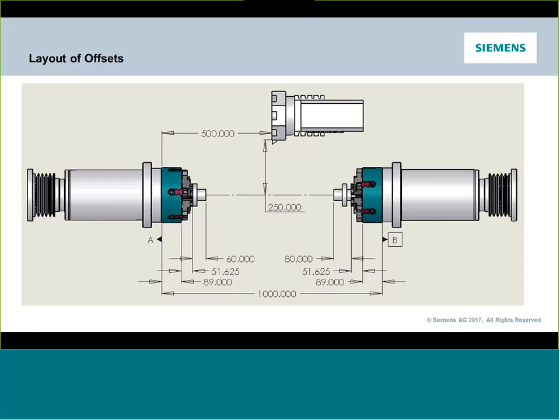Last thing we want to do certainly is be able to catch a tool while we're doing our transfer section. Now, the input is typically going to be set to diametric for X. So when we actually type in the value, you'll see I'll put 500 millimeters for both, but it's physically 250 millimeters away from the center line.